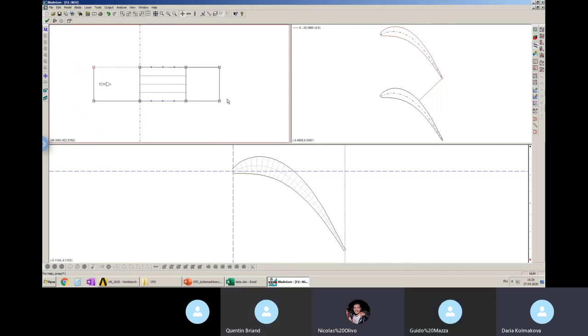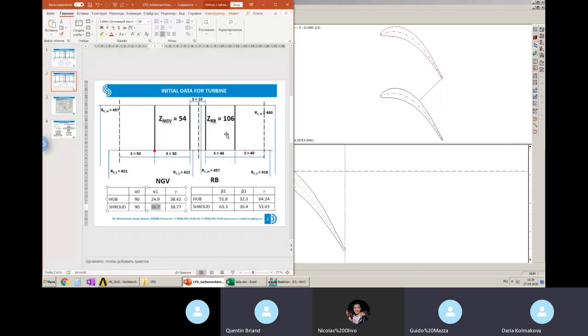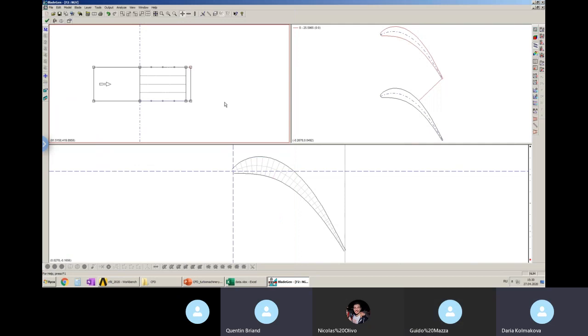I've chosen not a very good example for the turbine. I understood it now, because the blade is not very high. But okay, I will show you some approaches, and you will use these techniques for future tasks. And for the right boundary, the horizontal coordinate will be 55. Again, it's in the middle of the axial gap, and this is the boundary by which two blades will be combined. Okay.